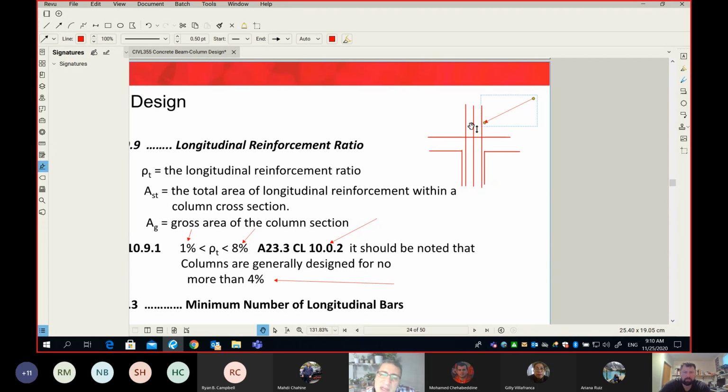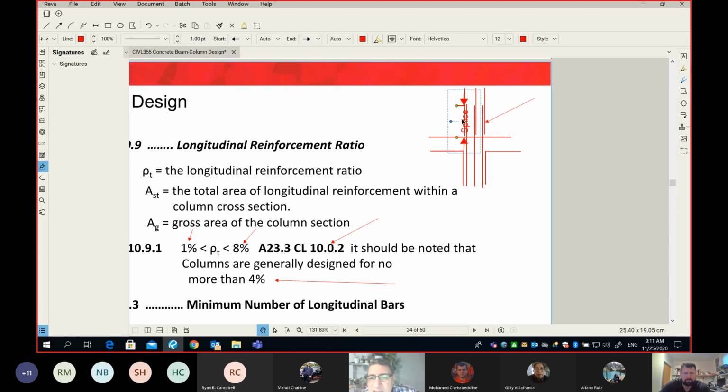And then for the next floor, we bring another cage, and another cage will be here, this way. They have a kind of a splice, and simply we place our next column. So this dimension here is called the splice, and we will talk about the splice later in our course, probably next class.